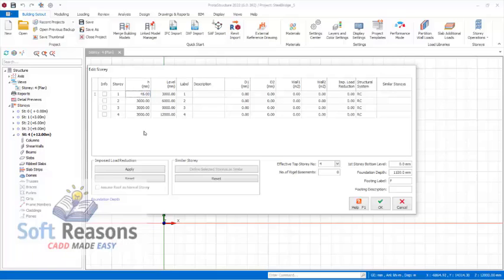So 450 in the sense that this is just a normal 450 to the normal ground level. Okay, so my story 2 is going to be 1500. The first rest landing before you take up to this story, to take up to this story should be like 2200. While these other stories we can go by 2500 right there, or 2600. Okay, so this is the story set out.